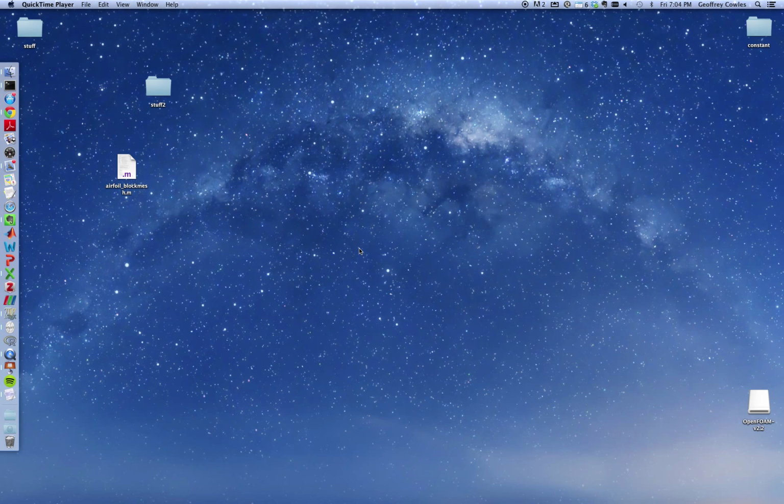Professor Coles. I'm just going to go over the part of the computing problem where we're going to use a Matlab script to generate the information needed by OpenFOAM to build a grid around an airfoil, a 2D airfoil, to do some flow computations, which we'll handle in a later computing problem. So I assume I've downloaded my airfoil block mesh.m.